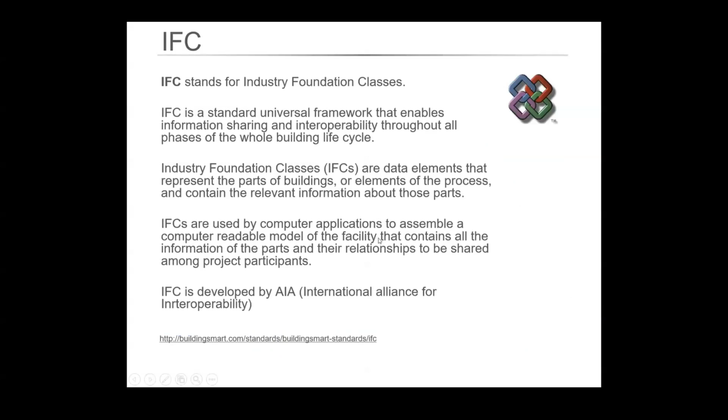So IFC, Industry Foundation Classes, that's our typical external file that we're taking in and out from engineers, HVAC, sprinkler designers, all those other people that we work with. So that generally takes the 3D data and allows everyone to see the model in a 3D format and has a lot of information assigned to elements within the model, so everyone can see what is what if it's been done properly.